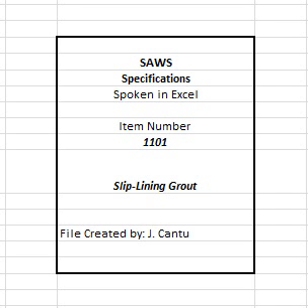2. Materials. A. Cement: comply with ASTM C150/C150M-12. Pozzolans and other cementitious materials are permitted. B. Fly ash: comply with ASTM C618-12a, either type C or type F shall be used. C. Sand: if provided, comply with ASTM C144-11, except as modified below.